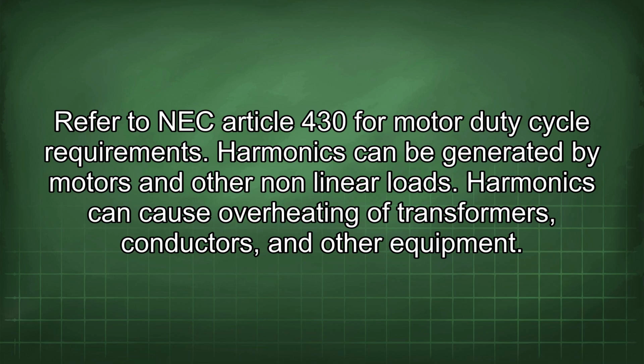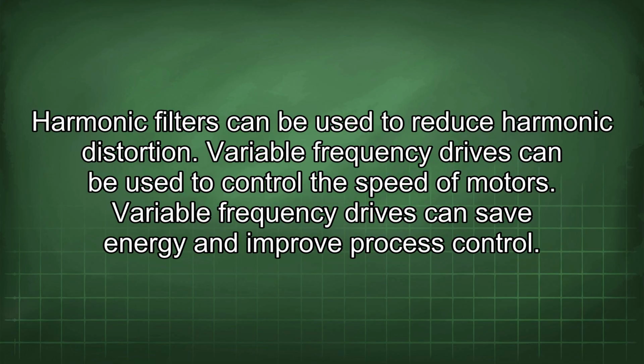Harmonics can cause overheating of transformers, conductors, and other equipment. Harmonic filters can be used to reduce harmonic distortion.